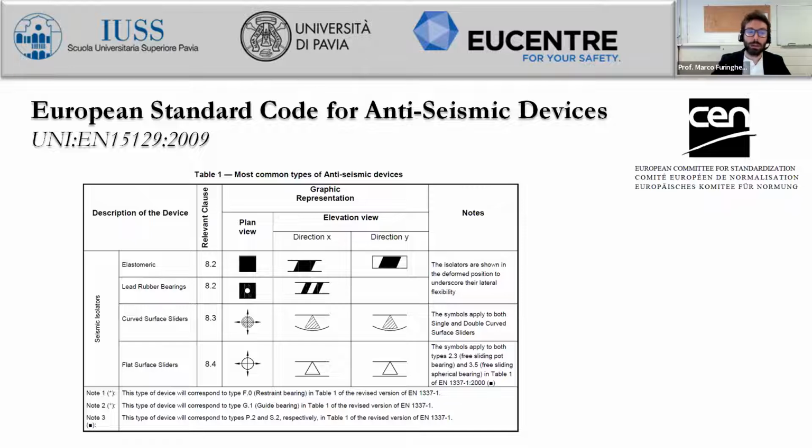If you have a reinforced concrete plate, you are inducing differential displacements, and so automatically bending moments, and they could be very large, because curved surface slider devices can move upward and downward a few centimeters, but if you compare a few centimeters with zero displacement, you have a relative deformation which is very high, and which could cause very large internal forces.